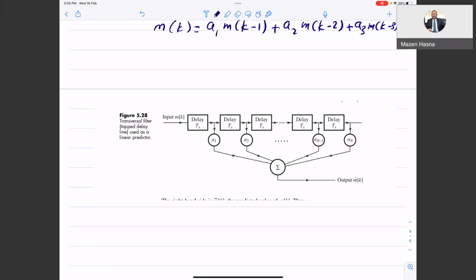And you have one more thing to do here, which is what we call a delta encoder. Delta encoder is a special case of DPCM, where you have very fast sampling, at least 4 times the sampling rate. You sample very fast, so now the samples will be very close to each other. So you use 2 levels only. If the sample is increasing, you send 1. If it's decreasing, you send 0. That's it. And at the receiver, having a reference, you keep adding and subtracting. And then you will have a very, very good encoder. But the condition is you have to have a very fast sampler.